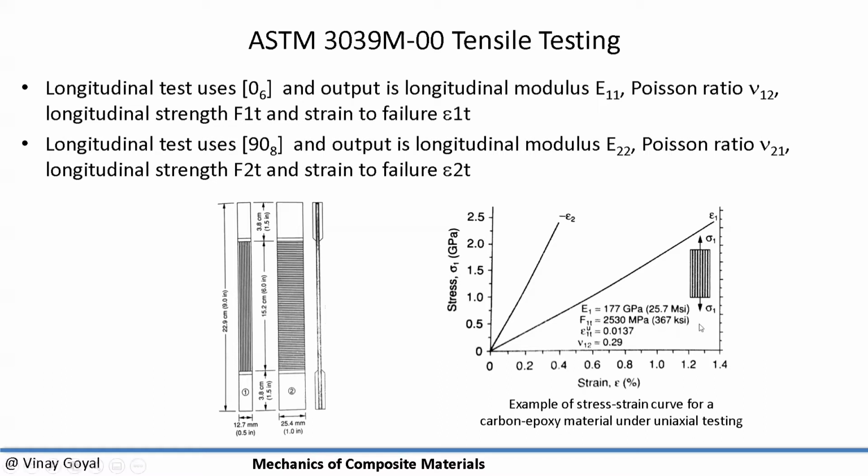The longitudinal strength can also be calculated. So if I apply a load, I can take it to failure. I don't get the necking that you see in metals. I'm going to get a brittle type failure. These kinds of materials will fail in the 1% range, 1.25 to 1.8%, most of them. And so as a consequence, you don't expect to have a lot of plasticity at all.